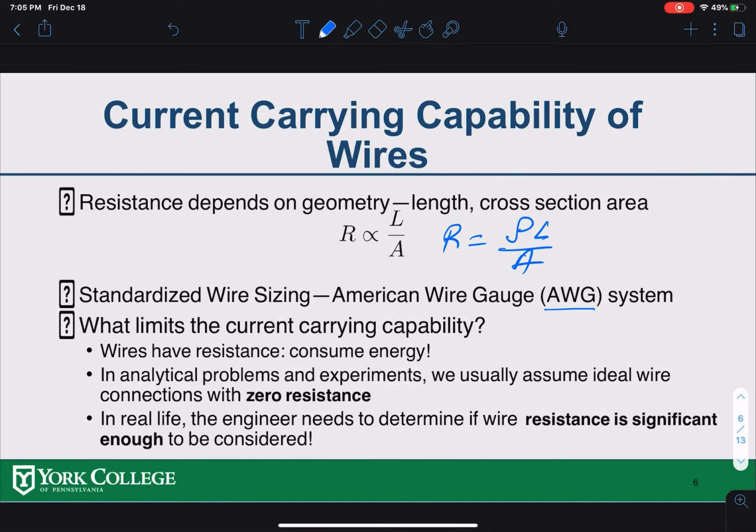So in that case, you have to use the worst case scenario. If you're using the wire by itself in open space, you can use the best case scenario for your current. For our application in the breadboard, we always assume that our wire has zero resistance. So we don't consider any resistance for our connection in the breadboard. We're gonna solve this problem in the class.